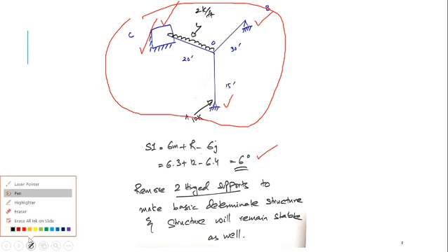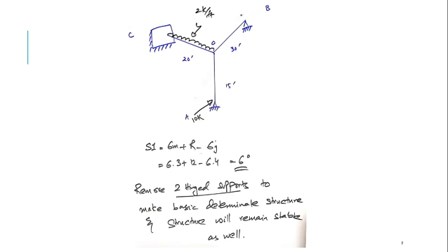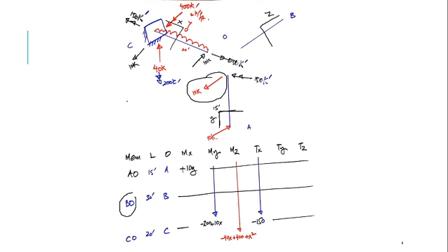Because there is no loading, one section is enough. Here, starting from A, there is only one applied load, so one section would be enough as well, and this would be Y. Starting from the support and taking this as section, you can see that there is a uniform loading and the magnitude of the loading is not changing, so one section would be enough as well.